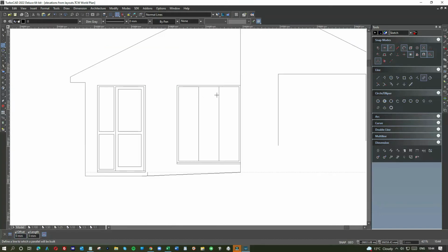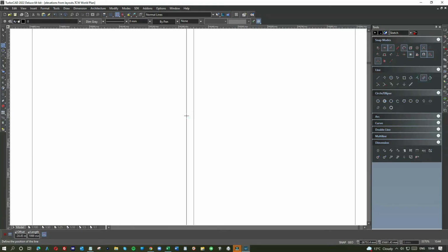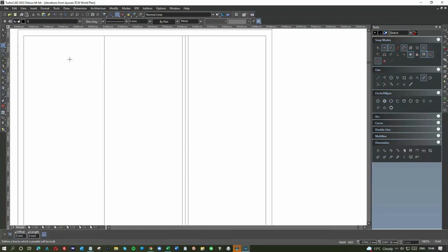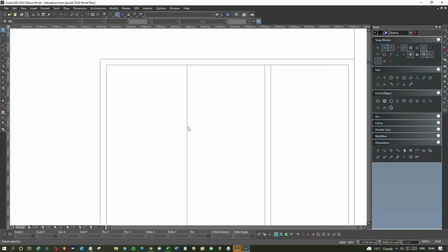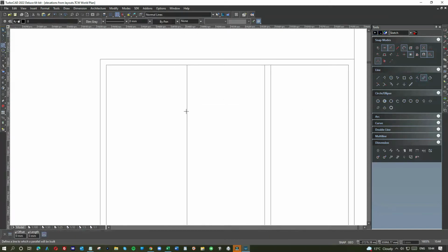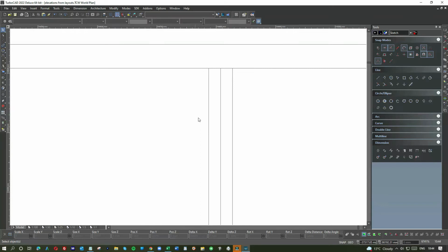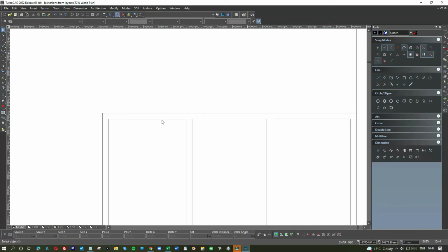But now these are centers, these are center points, so this is how I generally do it. Tab -20, tab 20. Now you see, if I remove the center line, I've now got a 40mm bar. So let's do it again. Parallel. We go tab -20, and then we go tab 20 and remove the center bar. Right, so let's get on with it.